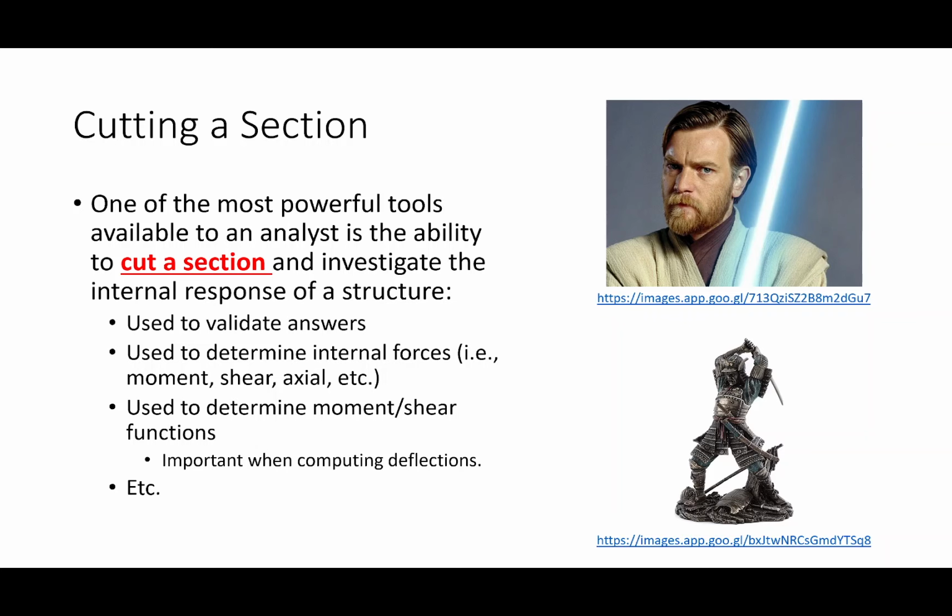We're going to be cutting sections throughout this semester for a variety of reasons. Things like validating the answers that we compute. Sometimes we'll need to cut sections just to analyze the structure. We'll cut sections to determine internal forces, internal shears, internal moments, etc. We'll also cut sections in order to write equations for the structure, specifically to graph moment as a function of x, or graph shear as a function of x.